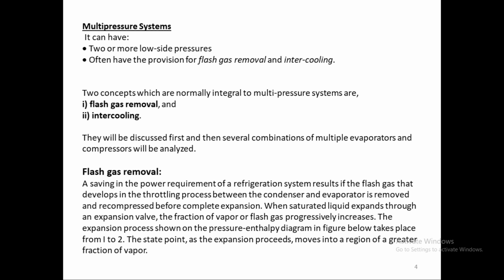So flash gas removal: a saving in the power requirement of a refrigeration system results if the flash gas that develops in the throttling process between the condenser and the evaporator is removed and recompressed before complete expansion.